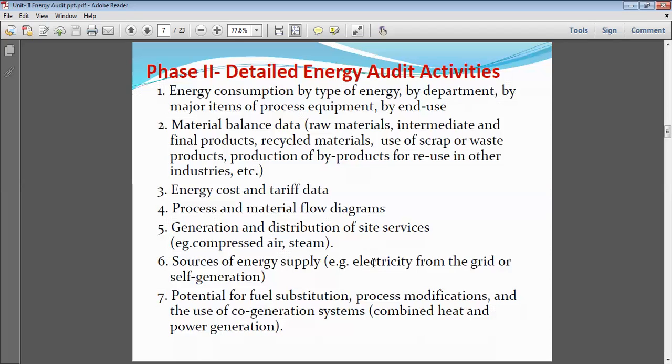So definitely, if the pipelines are very long, we can make some new routes which will avoid the number of bends, and the length and height of the pipe. It will improve the efficiency of the pumps, if it is related to a pump. If it is steam, you can understand where the thermal losses are, isn't it? Somewhere the insulation deteriorates or vanishes because of the aging effect. So you can provide proper thermal insulation, and definitely it will increase the overall efficiency of the system.